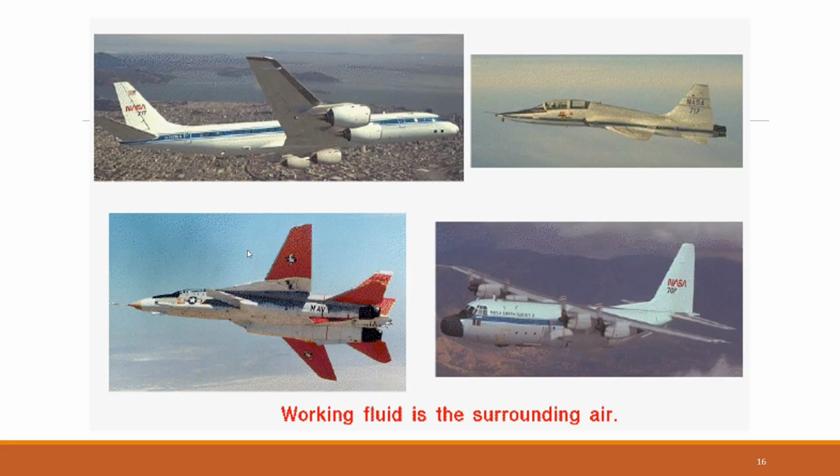At the lower left is an F-14 fighter jet, an aircraft built for air-to-air combat. While it also spends some time in cruise flight, its mission demands rapid acceleration and the ability to generate large amounts of thrust for short bursts during combat maneuvers. To achieve this, it uses 2 afterburning low-bypass turbofan engines. These engines can inject extra fuel into the exhaust stream, igniting it to produce dramatically increased thrust, a feature known as afterburning. This system allows the F-14 to reach supersonic speeds, though it consumes fuel at a much higher rate.